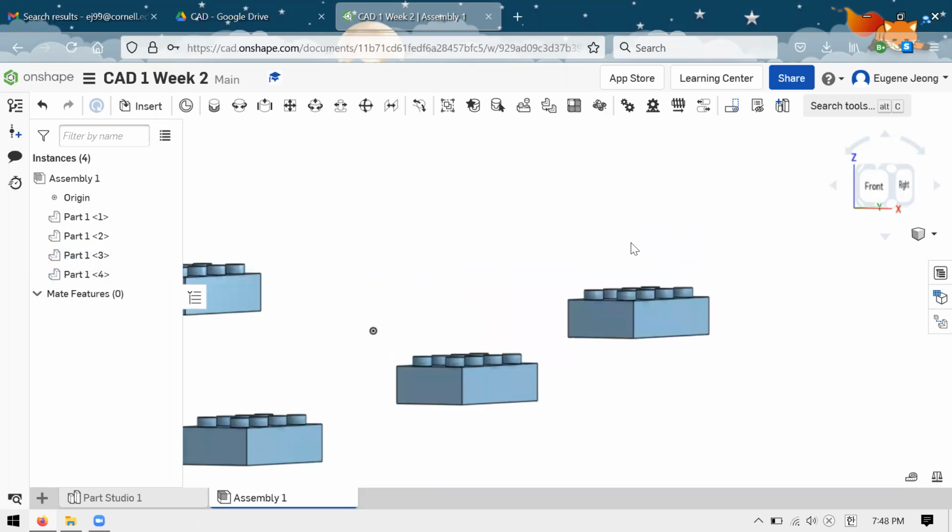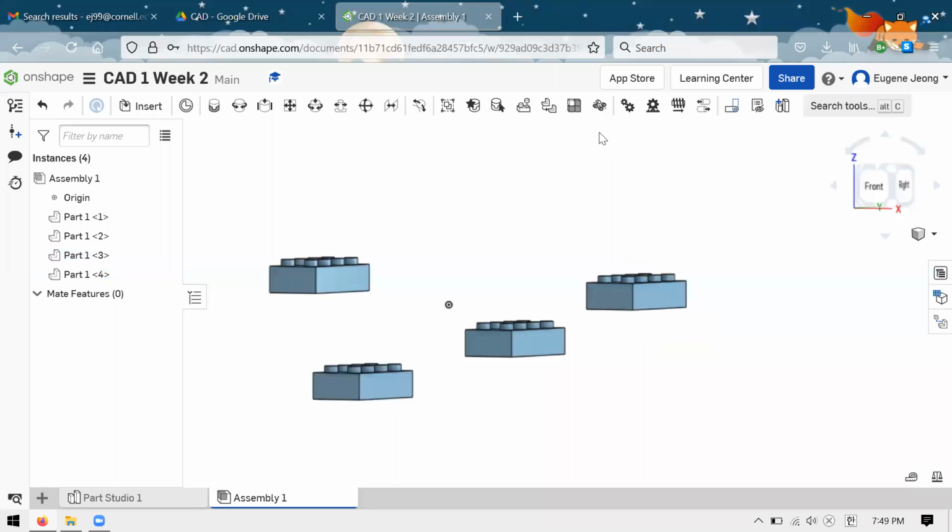So I do want to move it around, but let's say that this assembly isn't my last assembly. Once I make this assembly, I'm going to put it somewhere else. Like let's say there's another assembly that contains this assembly that contains parts, right? And for a very complex system like a robot, where it makes sense to divide it into multiple systems like the frame and the drivetrain, you're probably going to work with sub-assemblies. So it often makes sense to use the origin of your assembly as a logical center of your work.